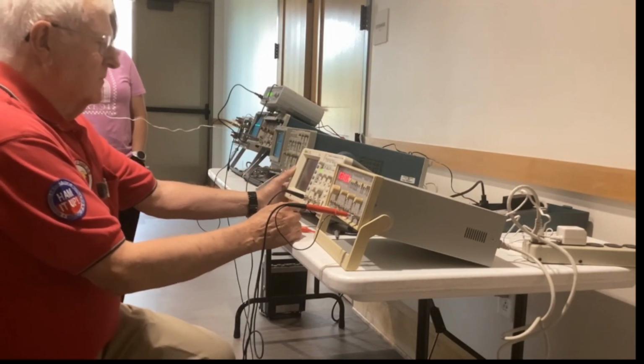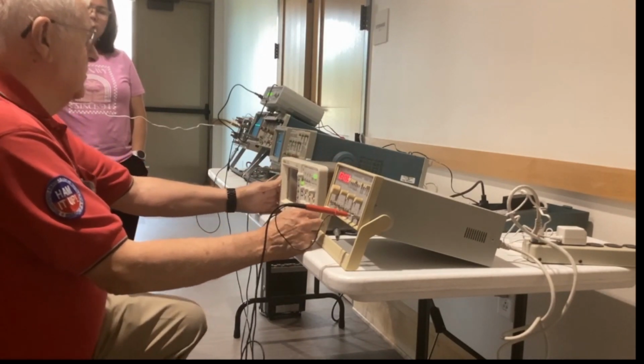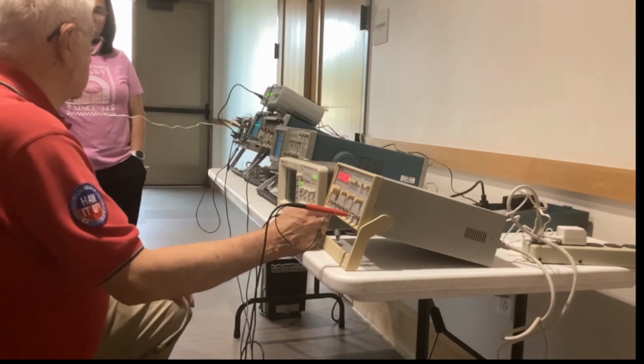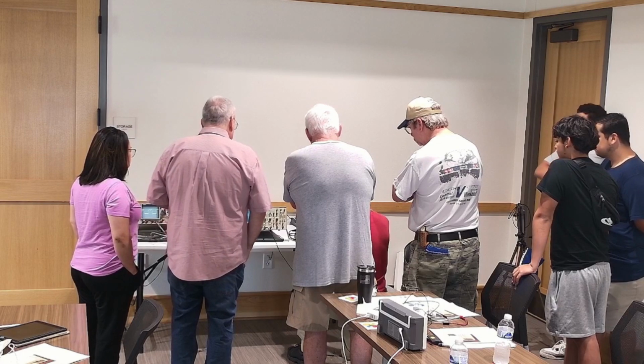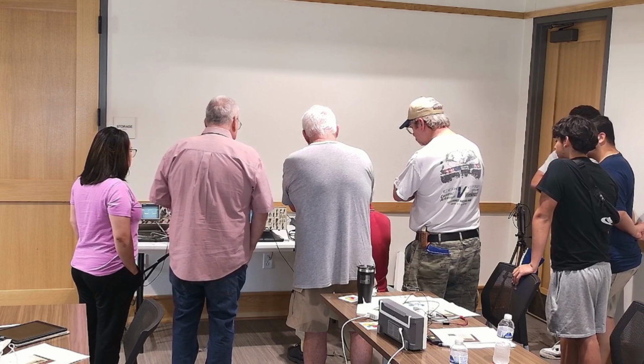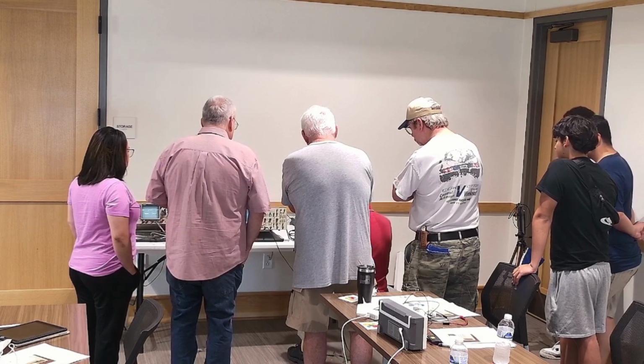And why would we want to do this? This is just to demonstrate looking at the waveforms. And if you're troubleshooting, oftentimes that will come in handy. Say you're troubleshooting a receiver and has no audio coming out the speakers. So you take a signal generator, put a signal in on the input of the antenna, and where the output's supposed to come out as audio, you put the scope on it and see if you have a signal there. Well, I got a signal. Okay, so that's it. I've got audio, but it's not getting to the speaker. Then I go to the next amplifier stage. Do I have audio here? Do I have it here? Do I have it here? Oh, this stage is out. So I know this transistor or whatever in that circuit is where the breakdown is.